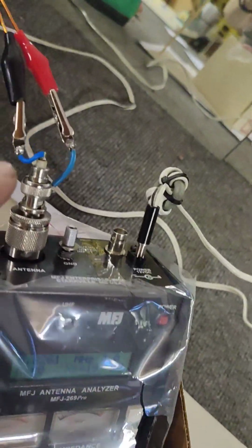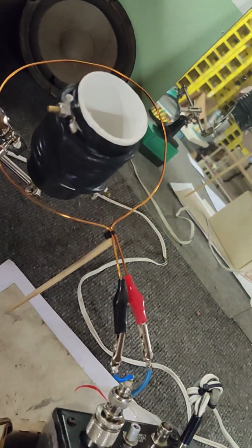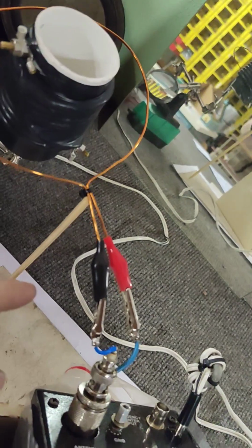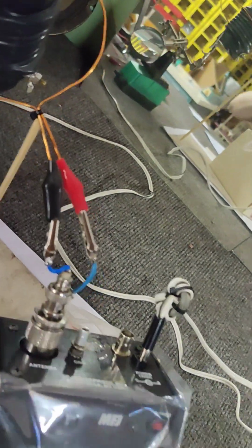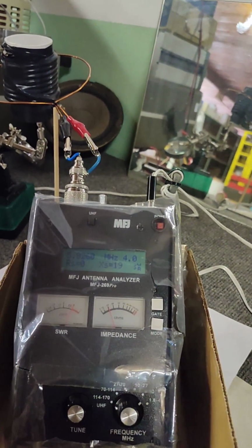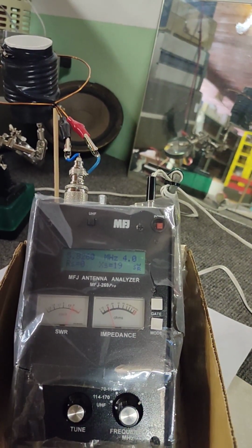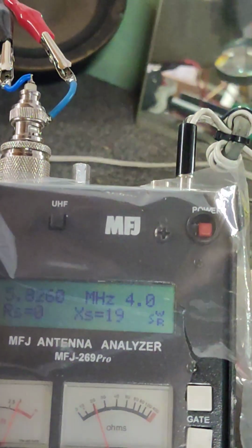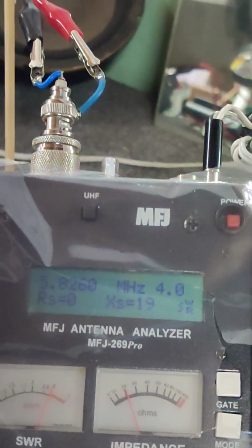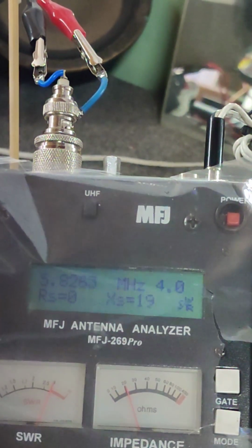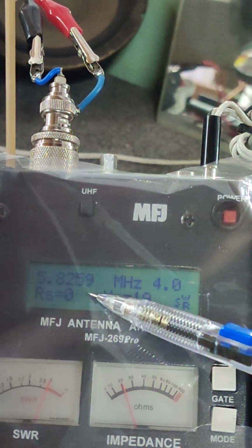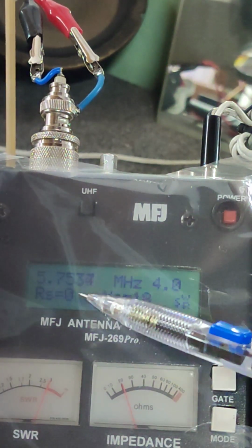And basically I have got my special little loop that I have made for the coaxial cable type of thing, which is connected into the MFJ. Now let's go and measure it and see what is actually happening. Of course, let me try to increase here so you can see it a bit better. Let's just do it this way. Okay. And that's fine. Okay, again, we're starting from about 5 something megahertz, from a lower frequency.